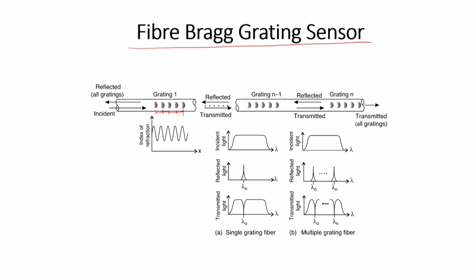Now, suppose I am having a system like this, which is subjected to something like a bending. So, that means you choose a system where you have this marking already given to you, okay? And then you know that corresponding to a light of a particular wavelength, what will be the diffraction pattern. But now, if I expand this system by the application of force, okay, then this grating separation distance also expands, because this whole thing is flexible. So, this distance changes. As this distance changes, that will also correspondingly change the diffraction pattern. So, the diffraction pattern will then become a function in a way of the force that the system is subjected to.